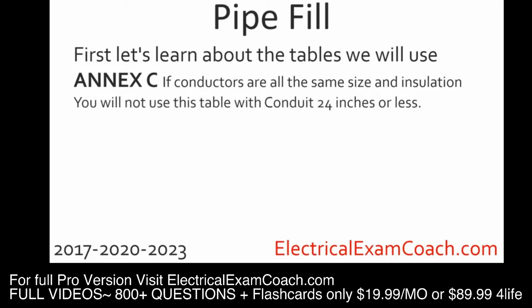You will not use this table if the conduit is 24 inches or less. Now the code book uses the term nipples, but I want you to imagine in your mind, anytime the conduit is 24 inches or less, you're not going to use Annex C. You're going to use the method that I'll teach you in lesson 7.2. You can head to page 712 of the 2017 and page 729 of the 2020. This video is 2023 compatible. You'll have to get to your page number for Annex C, and then you can follow along.